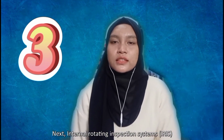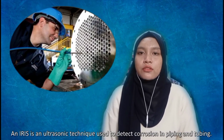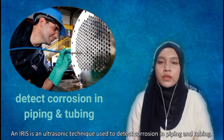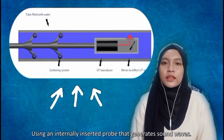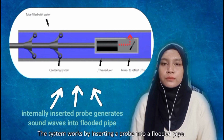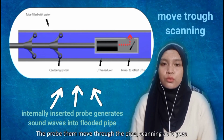Next, internal rotating inspection system, IRIS. An IRIS is an ultrasonic technique used to detect corrosion in piping and tubing. Using an internally inserted probe that generates sound wave, the system works by inserting a probe into a flooded pipe. The probe then moves through the pipe, scanning as it goes.